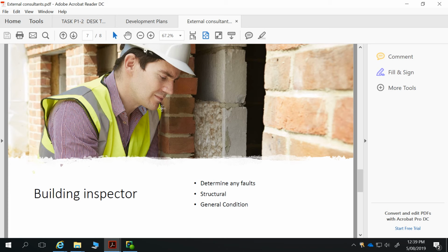Often people have built additions onto a building, poured a concrete slab and closed over those vents, and you get portions of the building which get inadequate ventilation. You get excess moisture in the soil there, and then that works its way up through the walls and starts eating away at the stonework and brickwork, whatever. So to have a building inspector spot those things and tell you, well, look, yes, we've got a problem with salt damp, and that can be mitigated through these rectification works, etc., provides fantastic information in regards to that.